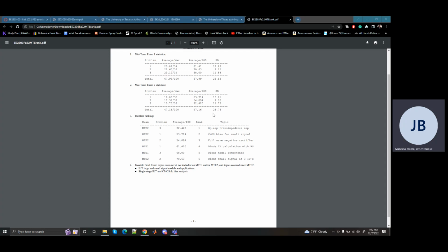So VP is really easy to find. We know that no current's going to go through here into the op amp. So this just becomes a voltage divider. VN is where you did that practice of using V out. You want VP and VN in terms of input and output voltages or sources. So VN in terms of that is going to be this voltage drop plus that to ground.